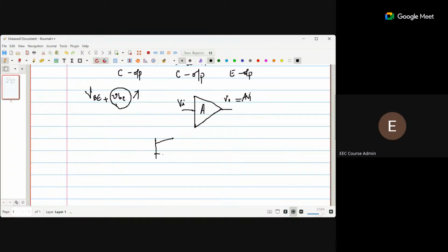So you have the NPN BJT, then the bias resistors R1 and R2, RC, RE. This much you had seen even in your week 7. So you have that power supply, and we had seen the DC analysis also. How do you calculate this? By Thevenizing the circuit, you calculate the base current, then IC is beta IB, then you find out VCE. All such things you now know. And now to the same circuit we have a few more components.